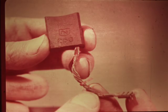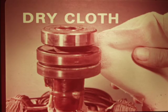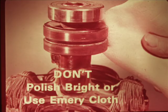Check that the wires to the brushes are intact, properly connected to their terminals, and that the insulation is not worn through to cause grounding. Clean the armature slip rings with a dry, lint-free cloth if necessary, or fine 240 grit sandpaper if there's any roughness. Use a very light touch. Be sure to remove all grit if you use sandpaper. Don't, however, attempt to restore their original bright finish, and don't use coarse sandpaper or any kind of emery cloth for the cleaning job.